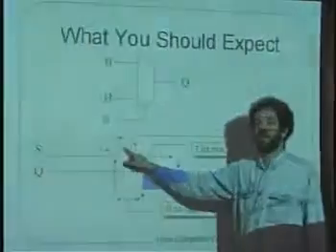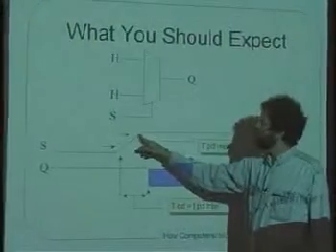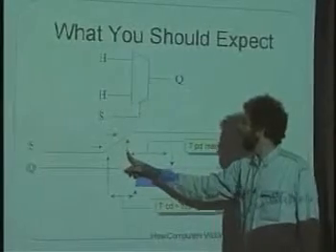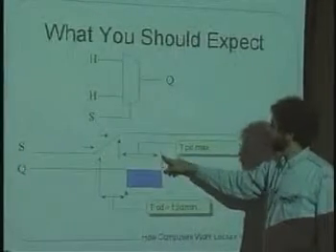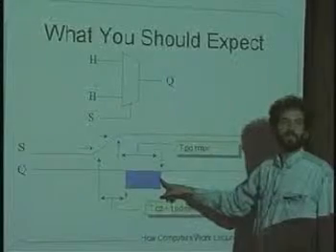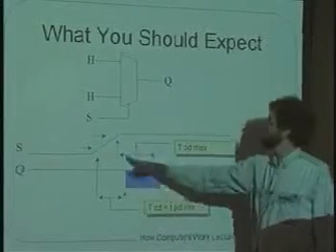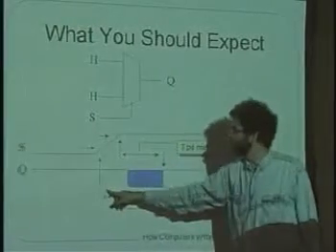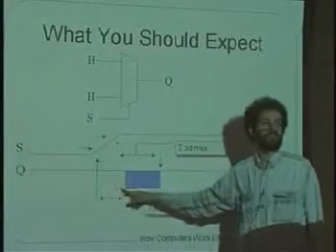And so we measure TPD max by asking when does S, if it takes some time to go from low to high, finally become the valid new value here, and when does the output finally come out with a valid value here. And this is the longest that that could take. And this time here would be the shortest that the contamination could happen.